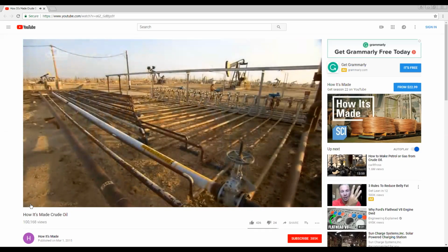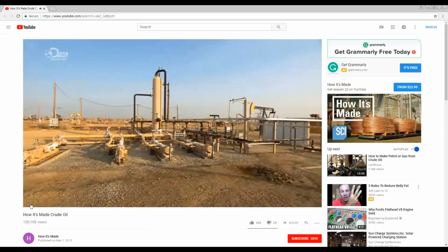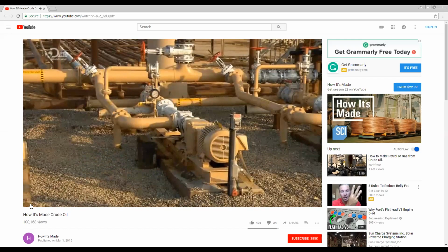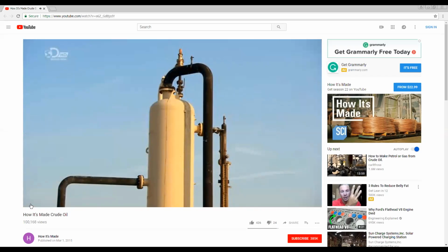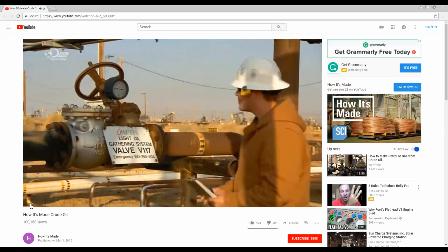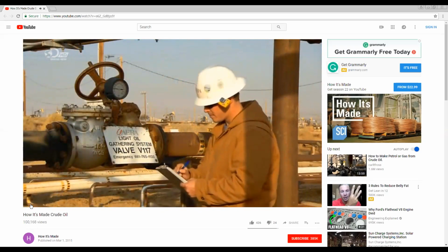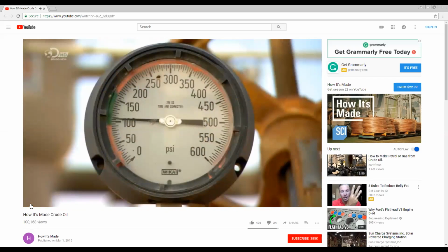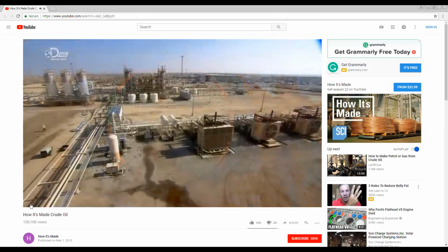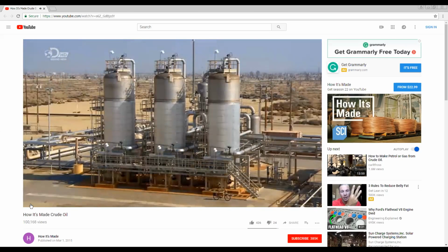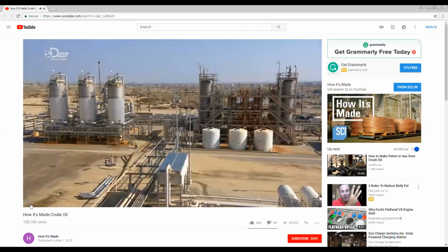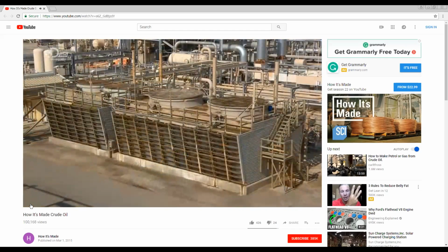The fluid from each well exits via a pipe, and the pipes from all the wells feed a main line, leading to a gas removal vessel. The fluid contains carbon dioxide, hydrogen sulfide, and natural gas, which has to be extracted. They naturally rise to the top of the vessel and exit via a pipe which runs to the company's gas treatment plant. There, equipment removes and treats the hydrogen sulfide, transforming it into sulfur, which a local farm buys to use as fertilizer.